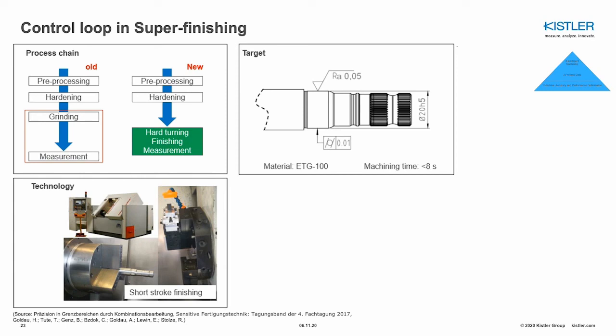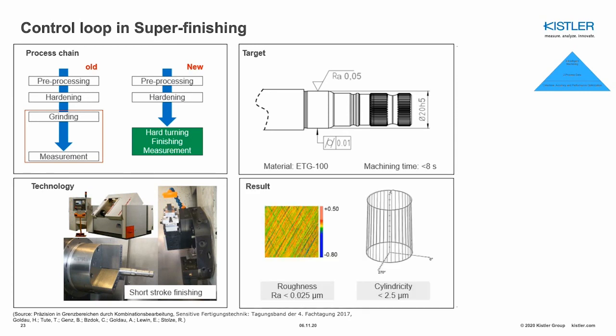So you need to integrate your force measurement here and build that correlation between the machine characteristic and the product quality parameters, which is important here, and then build your intelligence in order to steer your honing process in this case, so that the product quality parameters are within the limit. So integrate a force sensor to control the honing parameters online in the last step here.